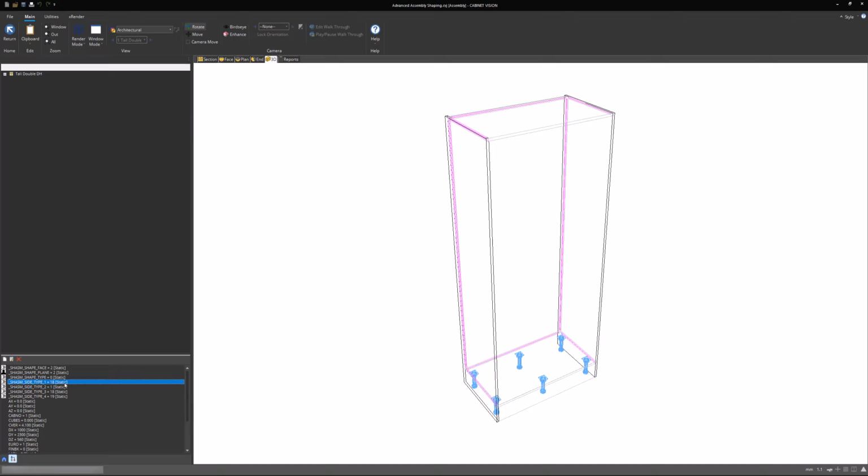So you'll see side type 1 I've got set to 18, side type 2 is 1, side type 3 is 18, and side type 4 is 19. So side type 1, 18, which is going to be, I think, an automatic end panel, which is this side here. Then we've got side type 1, which is going to be a face, and then 18 again, which is going to be an automatic end panel, and then 19, which is either an unfinished back or an automatic back.